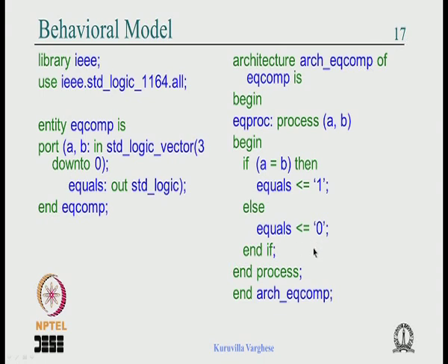And as I said, it goes sequentially from top to bottom. So when the simulator computes the behavior, whenever there is an event, it goes from top to bottom once for a particular event. Otherwise, if a second event happens, again it goes from top to bottom.